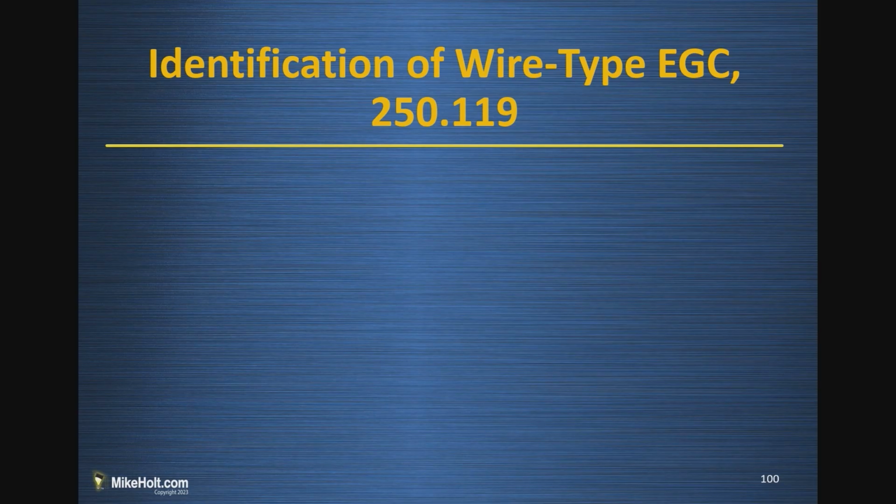Okay, let's identify. Mario? Yeah, I just want to make a comment that we just went off and listed a list of equipment grounding conductors, and in accordance with UL, the fittings for those metal conduits, tubings and metal cables are also listed for grounding.